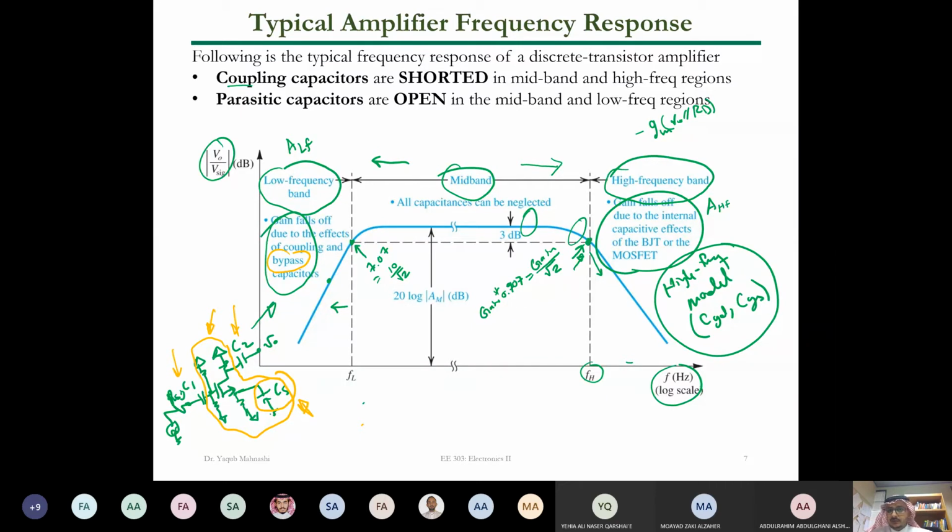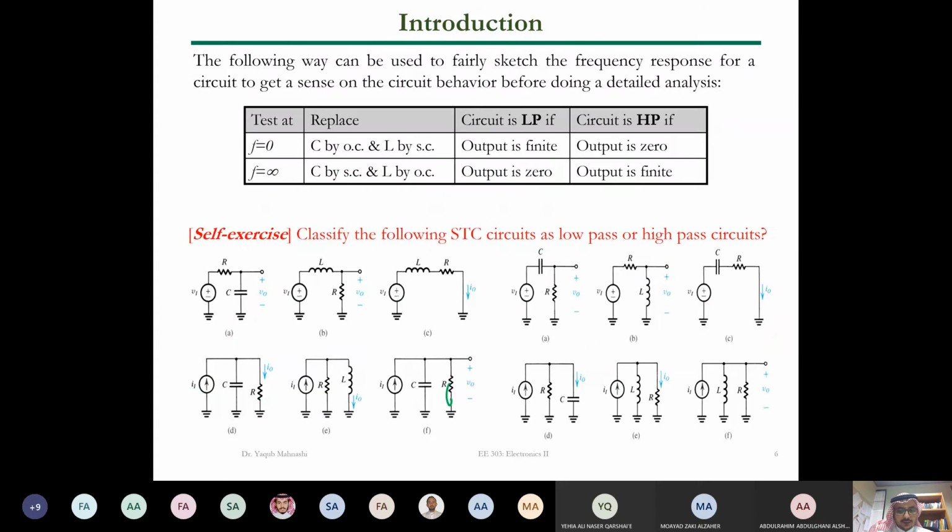But your point is logical: I don't want to lose my signal. I don't want to use 30% of gain reduction, which is very large. So that's why we may want to use less than that. For example, if you have 1 gigahertz of bandwidth, you may want to operate it at 850 megahertz instead, to be on the safe side. And if you get an application with different amplifiers, and the application requires 1 gigahertz operation.